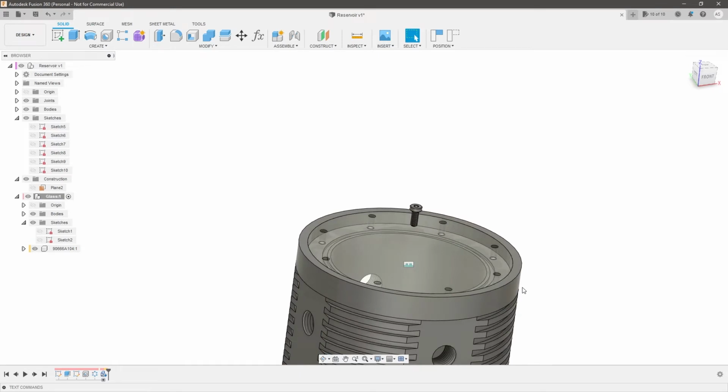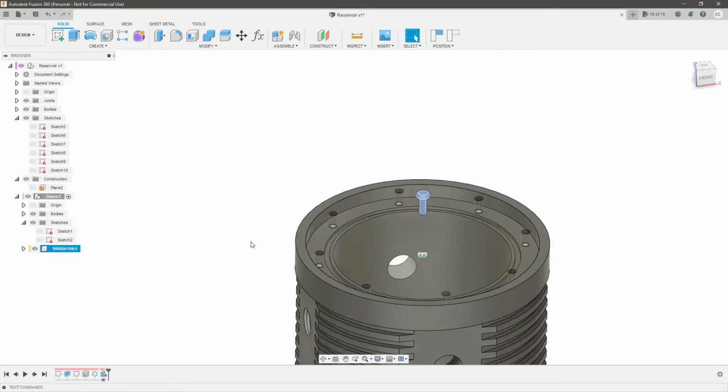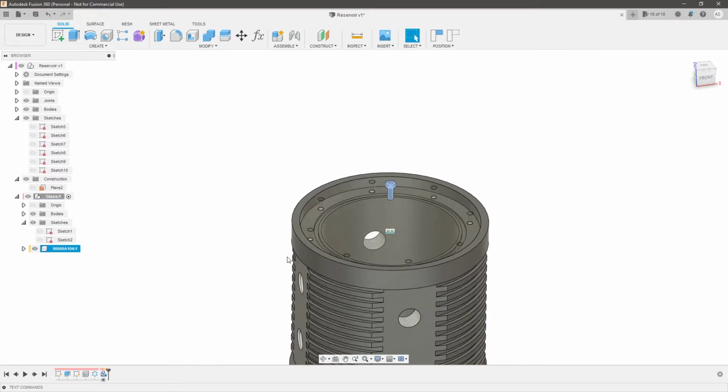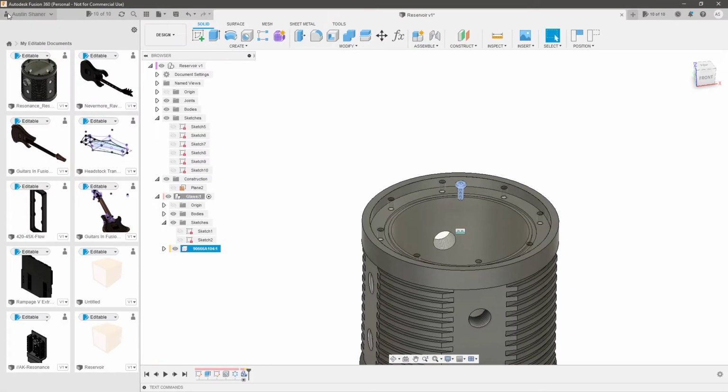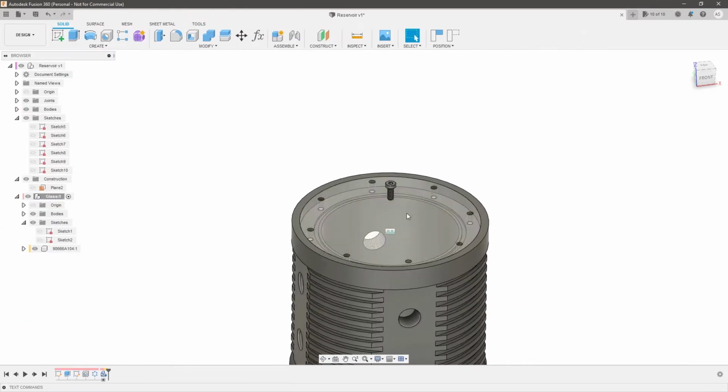Now, this is still basically top down, not bottom up, because this bolt that we've inserted only exists within the context of this assembly. It doesn't exist in any other files or folder structures that I have on my computer. So I can't really reuse this between different designs. So this is an important thing to remember.